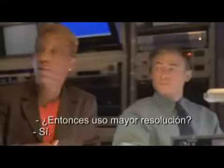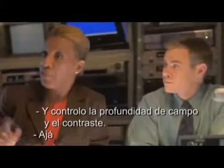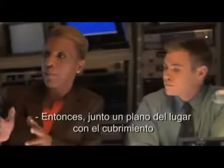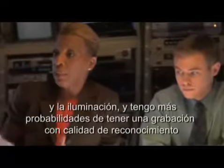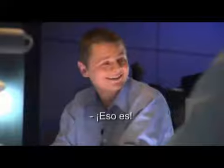So I use higher resolution and control for the right depth of field and contrast. And then I put together a site plan with the correct camera coverage, positioning, frames per second, and lighting, and I'm more likely to get a recognition quality recording. You got it.